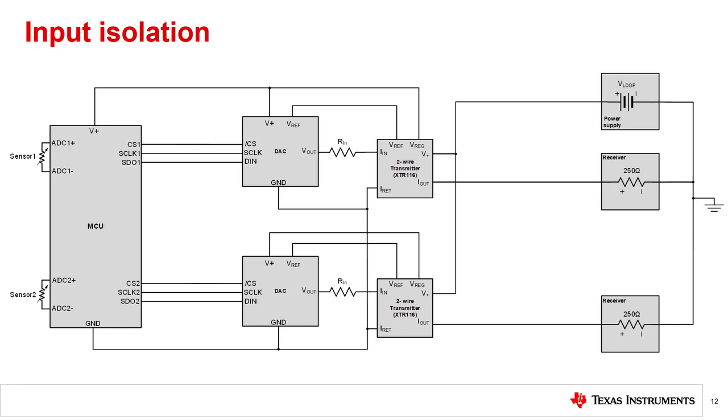As seen in a previous video, multiple transmitters connected to the outputs of one multi-channel digital to analog converter will create conflict between the IRETURN pins of the transmitters. The voltage at the IRETURN pins needs to float in order to produce the correct current output. So if multiple IRETURNs are tied directly to one ground pin of a digital to analog converter, they will not be able to float at the correct voltage.